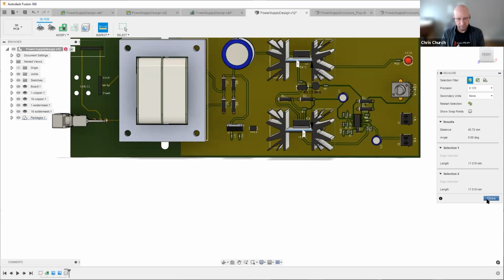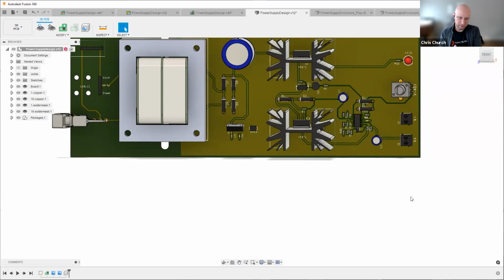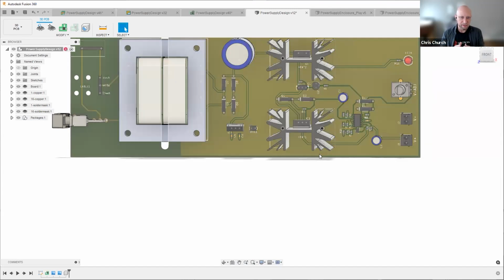So this is something, by looking together at this design and thinking about the manufacturing process, we can look at and say, for a more repeatable build, we want to turn that bottom, the heat one, around so that the screw is coming in from the outside, so that we can use a very standard process of just coming in with a screwdriver and attaching those. It's going to be lower cost, faster, more reliable and less likely to damage that board. Excellent.